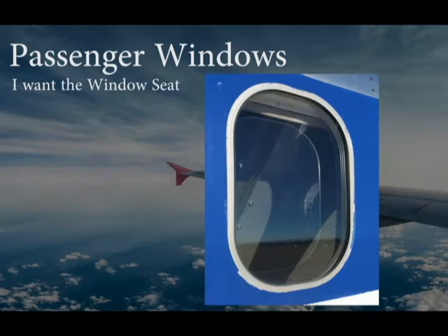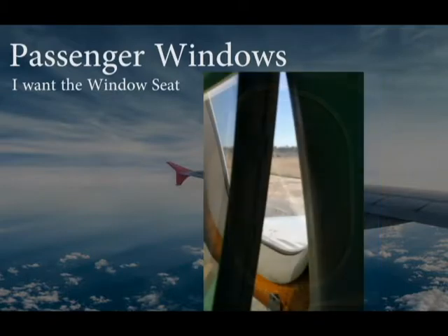Next up are the passenger windows. The passenger windows have a curved nature to them, despite being moderately rectangular. If the windows were to have corners, there would be stress concentrations on those corners. As these windows are not experiencing the same pressures as the forward windows, they do not have to be as robust as the windshield, and thus require fewer layers. The cabin windows only consist of 3 distinct panes: the outer, middle, and inner panes, along with the required protective coatings. Generally, the structural panes are made up of the same acrylic that is sometimes used in the forward-facing cockpit windows.